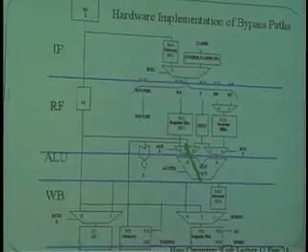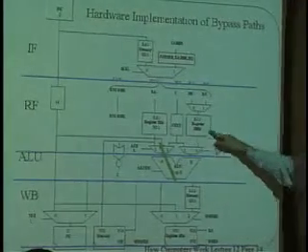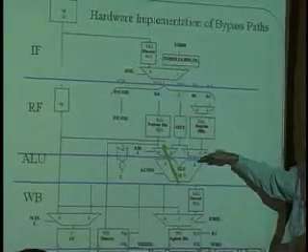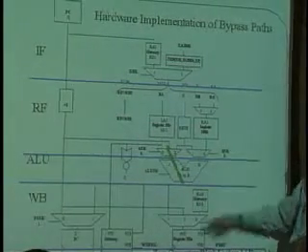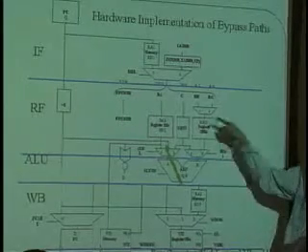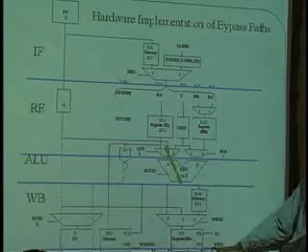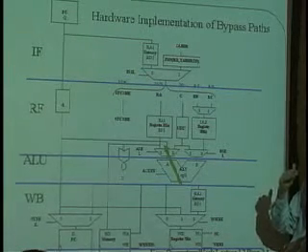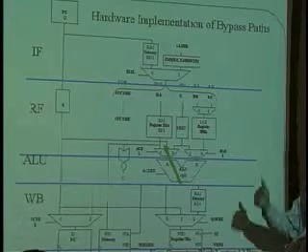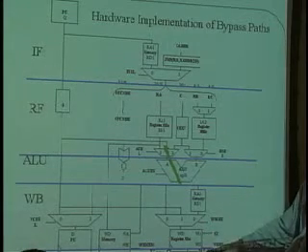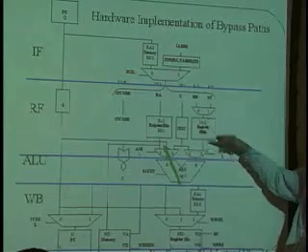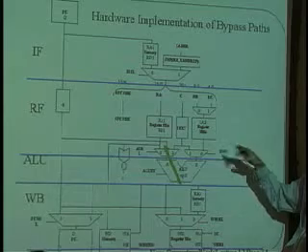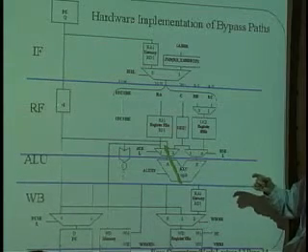What's wrong here? What's wrong here is that if you think about this cycle, we have register file, and how many registers are in the middle? 1, 2, 3, right? There's 3 registers in this feedback loop. And we used to only have 1 register. 1 register worked because that meant that there was 1 unit of delay between one instruction and the next one. So you could write a register, the clock could go off, and then the new value would come out here. But now we've inserted 2 more time delays in this loop. And as a result, it now takes 2 extra clock cycles before data gets ready.